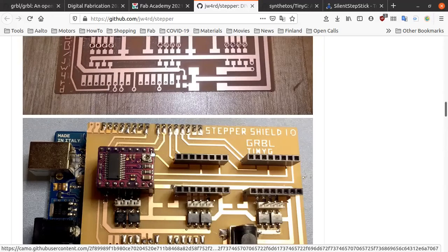So in terms of quality, price, there are different things that you might need at a given point. So let's say you want to make a cheaper machine and you don't care if it's silent or if it's precise, then you can go with a cheaper step stick and stepper driver. And then if you need higher quality, then in some scenario you might go with a better stepper driver. So it's just the replaceability of it. This makes it much easier to experiment and replace the specific motor driver.